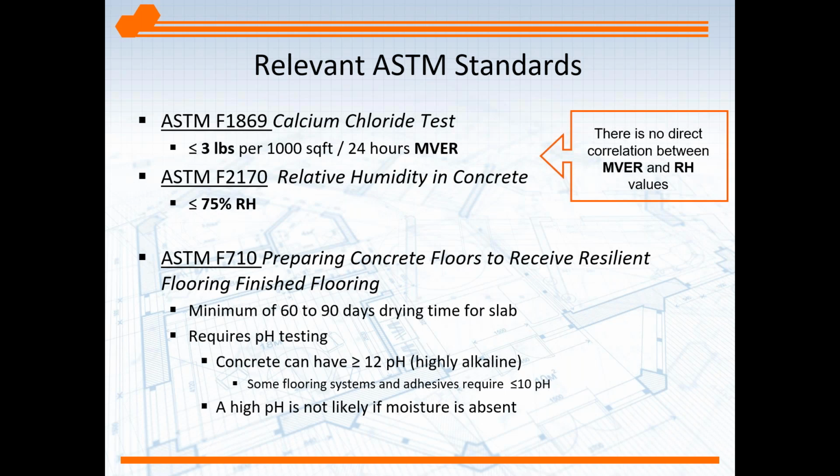Some flooring materials, as well as their adhesives, require a lower pH than what you get with new concrete or concrete that has moisture being driven through the slab. And a high pH is not possible unless you have moisture present. And as I mentioned earlier, ASTM F710 says it's for resilient flooring, but other flooring manufacturers will conform to the